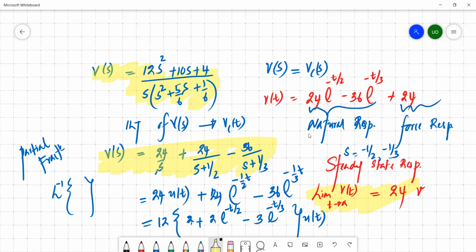So if you just convert this time domain circuit immediately to the S domain by replacing these inductors, capacitors, and sources with corresponding S domain quantities, then the entire calculation is in the S domain. Then you can do the calculations and get the final results again as a function of S, and then you can apply partial fractions and split into smaller entities and do the inverse Laplace transform, which gives the time domain response. So it basically contains both the natural and forced response together.